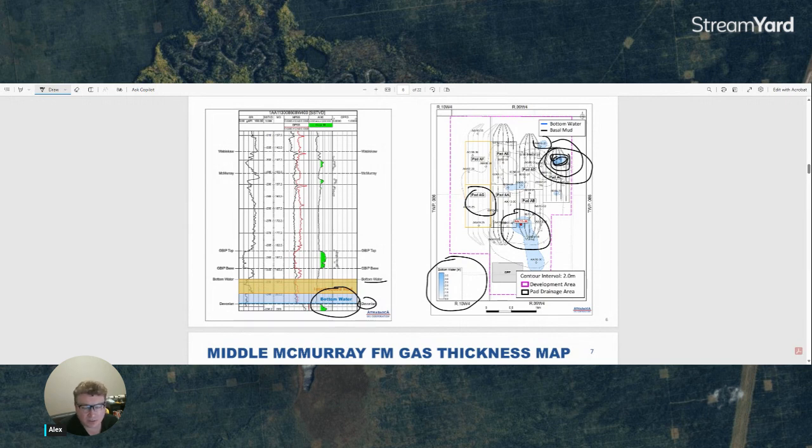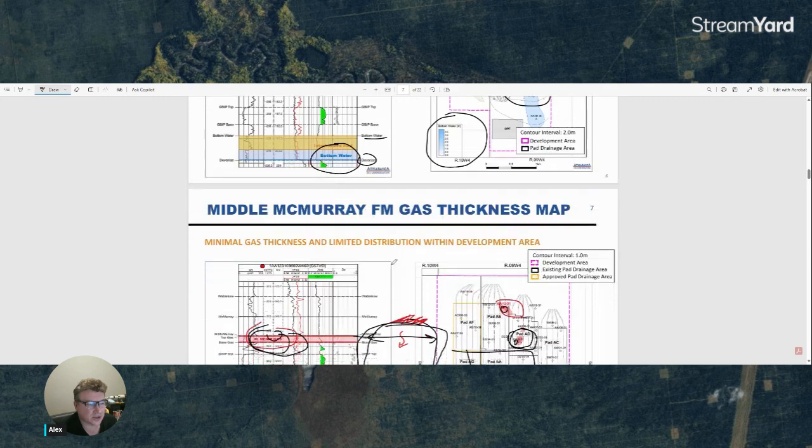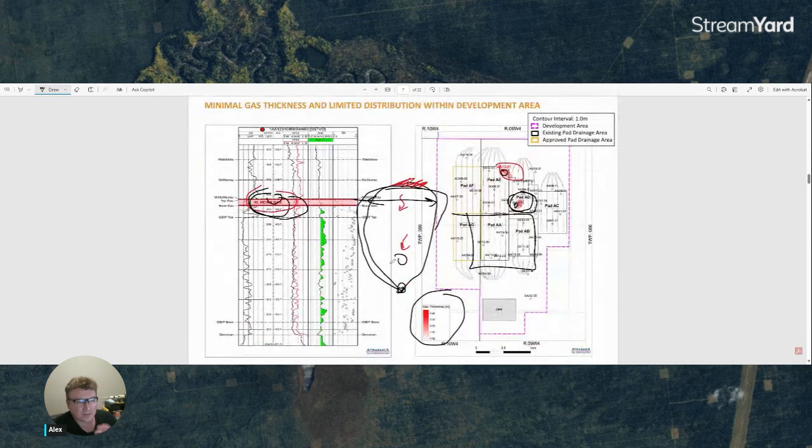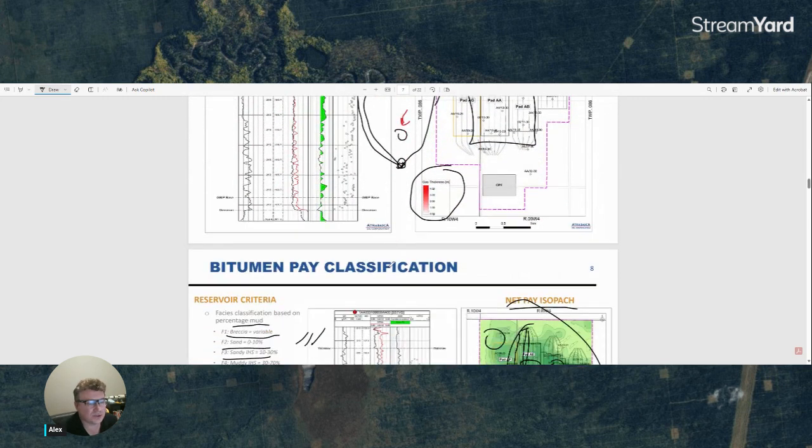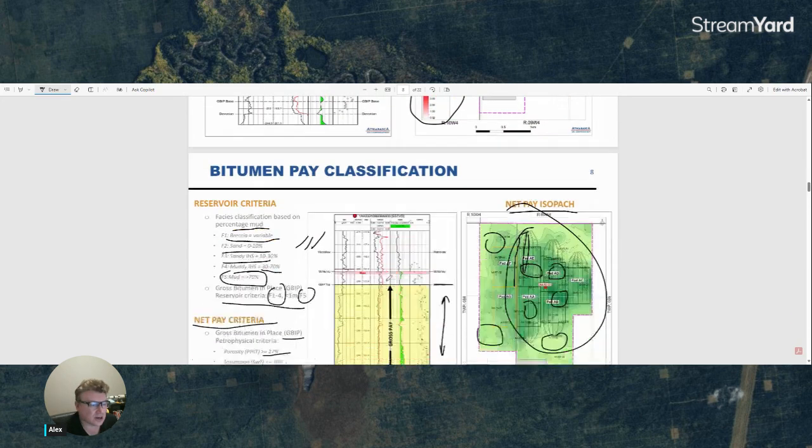What if you produce a little bit more water than what you injected, where ideally this ratio should be 1? Now you need to keep an eye that you're maintaining bottom hole pressure, injecting a sufficient amount of steam to pressurize the reservoir, or NCG, so the water doesn't enter the chamber and reduce the oil production rate by modifying the water cut.